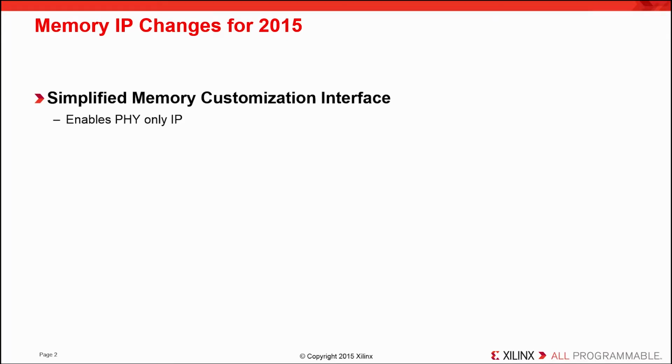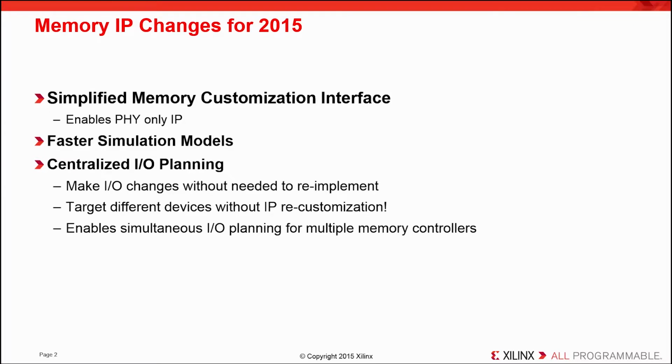Firstly, we've simplified the memory interface quite a bit, and we've enabled the PHY-only implementation without the memory controller. We provided a faster BFM model for simulation, and most importantly, we've centralized the I/O planning tasks, moved it out of the IP and into the Vivado I/O planner with the rest of the design.